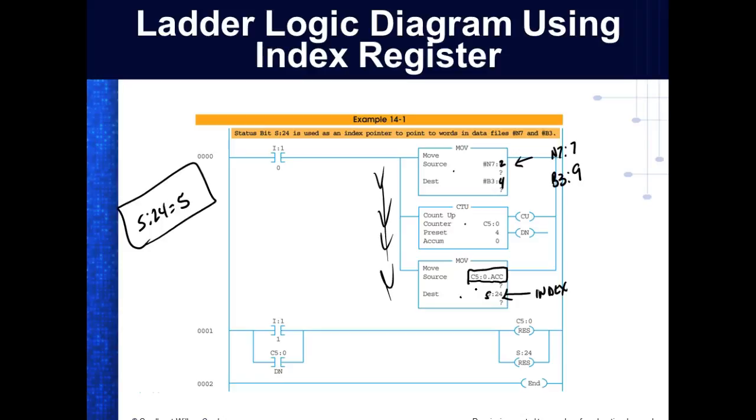And every time you move the drum switch, it makes a different set of contacts. But what can you do? Well, you can go in there and manually change those contacts. So you could have 6 positions, and you could literally program what you want to do for each of those 6 positions. But the problem is it's mechanical, so what would you have to do? If you wanted to change the sequence of these motors, you'd have to go in and move the tabs. You'd have to break it apart and put the tab through.